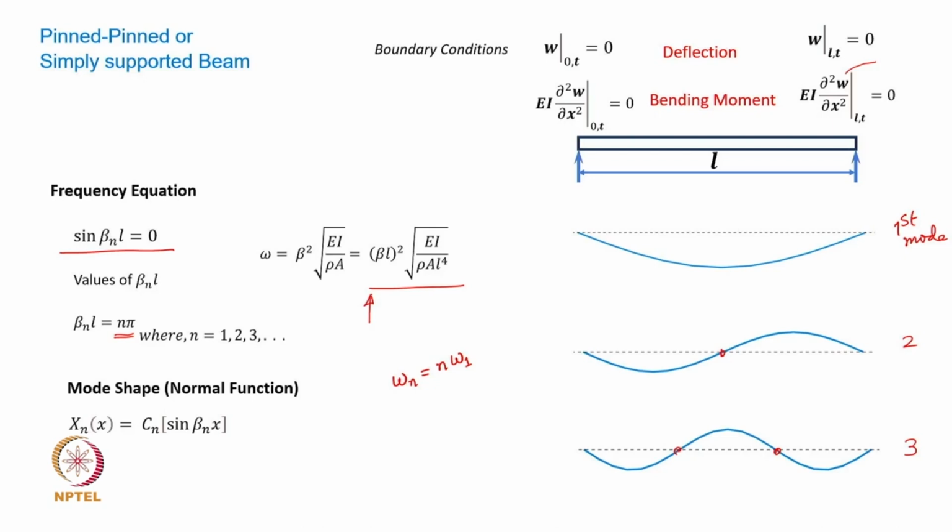a discretization method, by segmenting the total length of the beam into several sections and then using numerical methods to get natural frequencies, of course at the expense of computation cost. But then you can increase the number of segments so that within a segment the change in the cross sectional dimensions can be minimized to almost 0. But that's the situation. There are pros and cons here. These expressions are essentially the most accurate solutions.